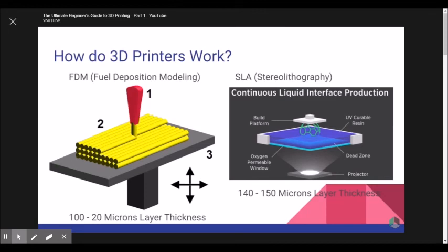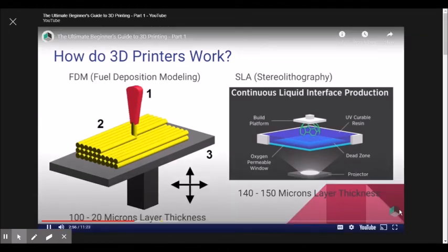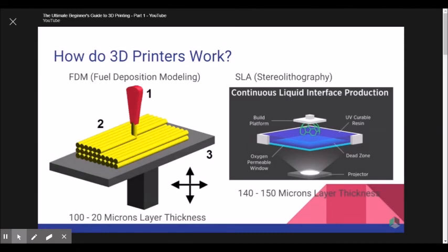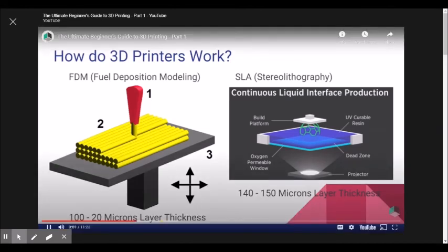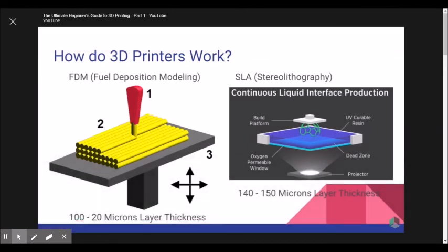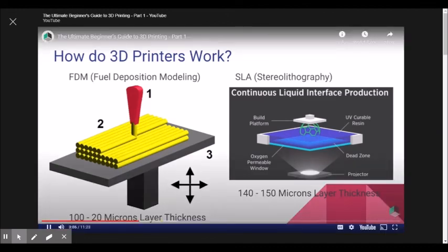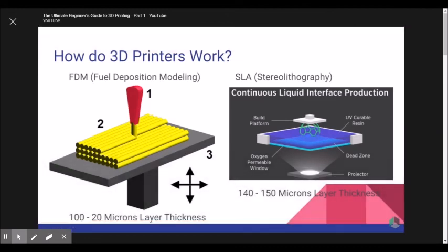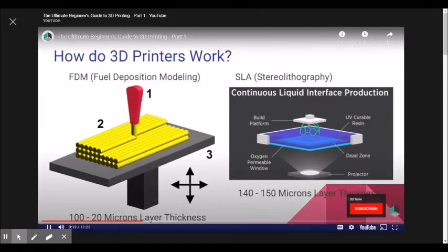And like I said, FDM is an additive process. It uses a spool of filament plastic and extrudes that through a hot nozzle at 195 degrees Celsius or around that temperature. It extrudes it through a cone-shaped metal piece called the hot end, out into a really, really small, thin strand. The printer moves around in three-dimensional X, Y, and Z planes and squishes those layers onto the bed on top of each other, as you can see here. So that's the most common type of 3D printing.